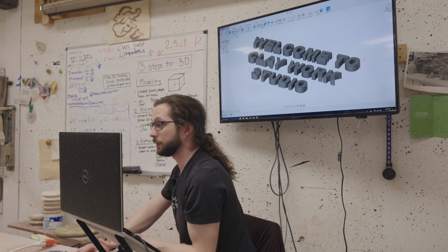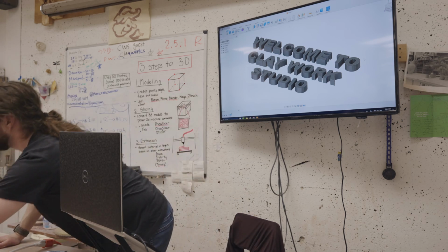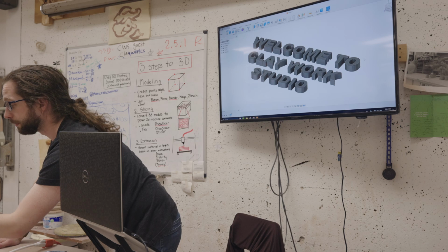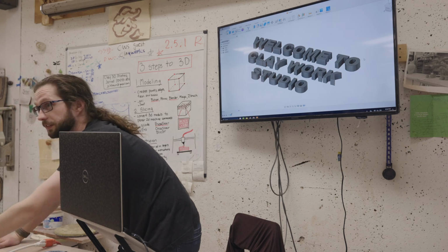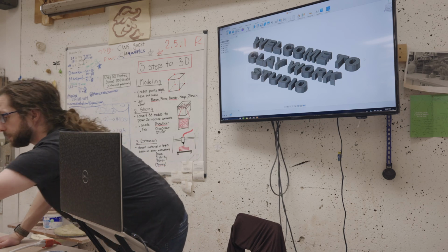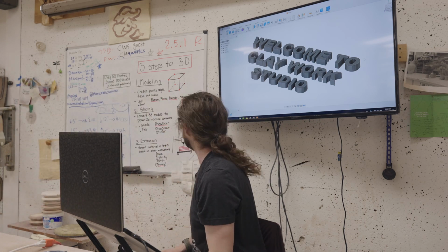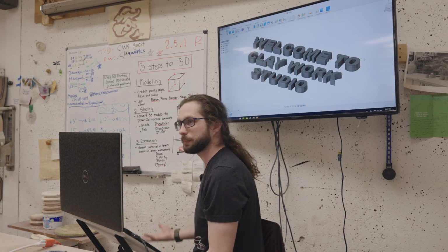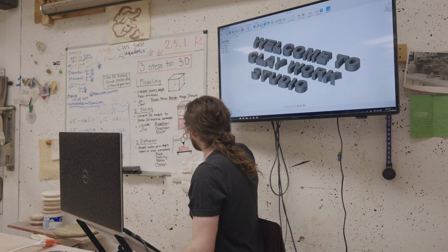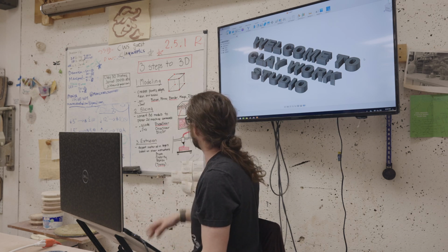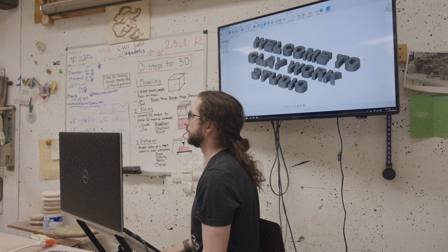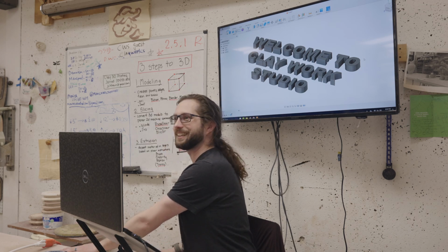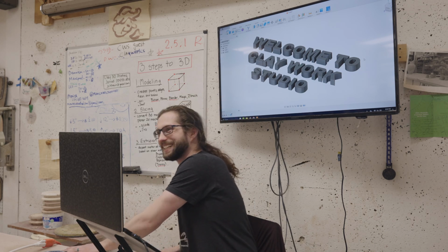And there are mediums in between, right? This form's hollow, but this form is a good example. You can't see in it, but in order to support these curves, it has ribs inside of here, and you can define how solid you want something to be in the slicer. And so we'll talk about that because there are certain shapes that we can't print just due to the nature of printing slice by slice. And so we'll talk more about that next week when we're talking about the slicer. But don't be surprised if you go home, make some models, come back next week, and I tell you, this looks amazing, but we can't print it.